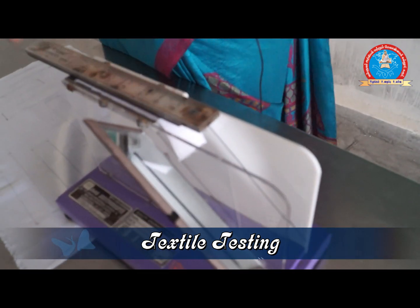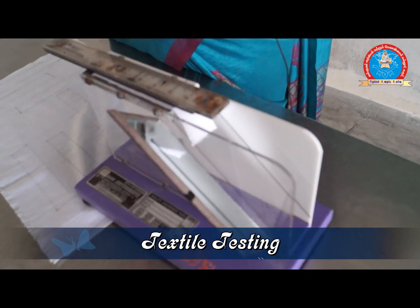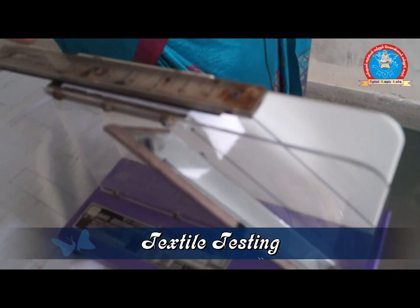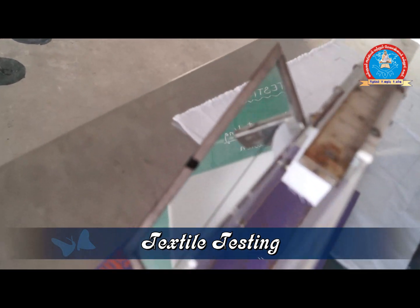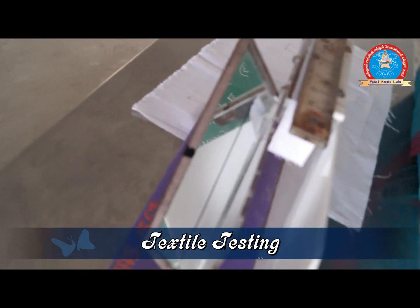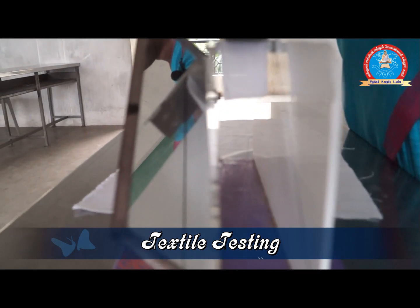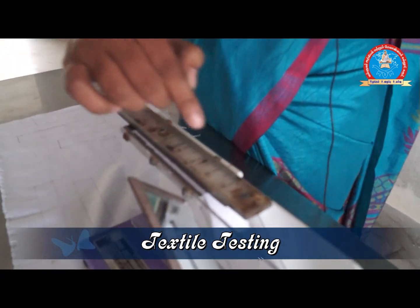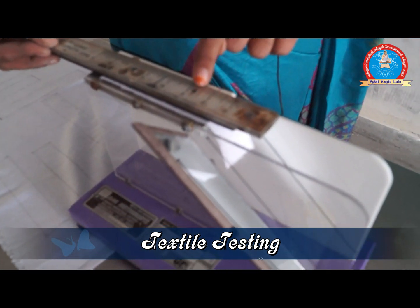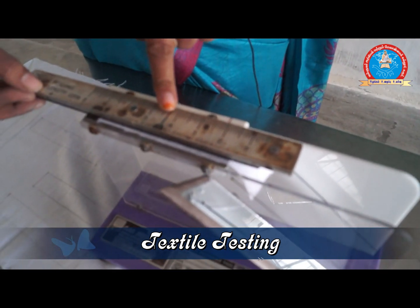After it meets the index line, we check whether it is correct through the mirror. With the help of the mirror, we see whether the fabric meets the index lines. If it meets, we note the reading from the bending length scale.